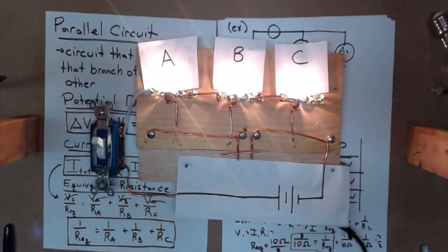You know, if you go in your kitchen or your living room and you look at the lights above when you turn the switch on, if one of those bulbs goes out, does your whole living room go dark? No, right? So you can kind of infer from that how your electricians must have wired those lights together, right? They had to have been in parallel.